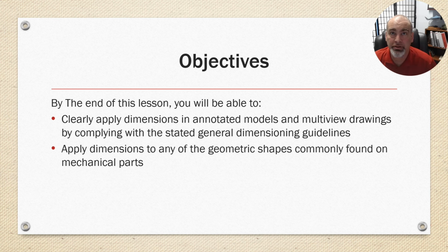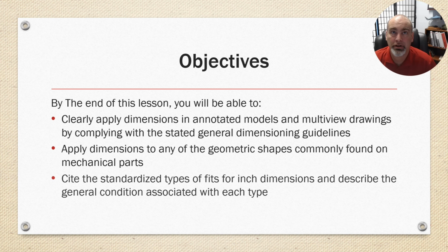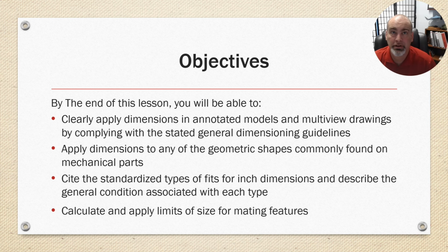Apply dimensions to any of the geometric shapes commonly found on mechanical parts. Cite the standardized types of fit for inch dimensions and describe the general condition associated with each type. Calculate and apply limits of size for mating features.